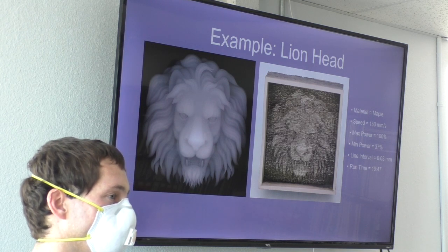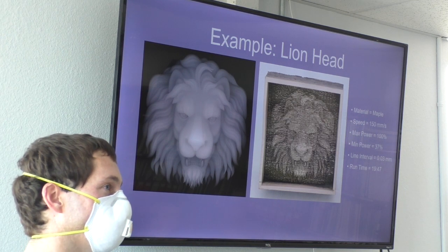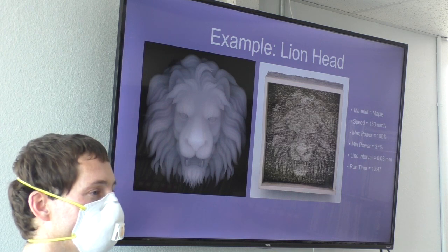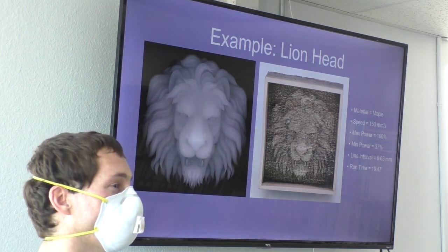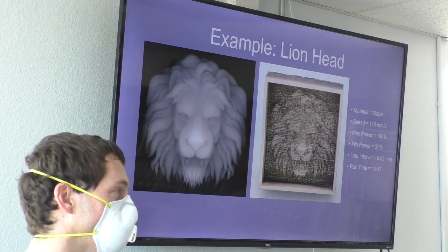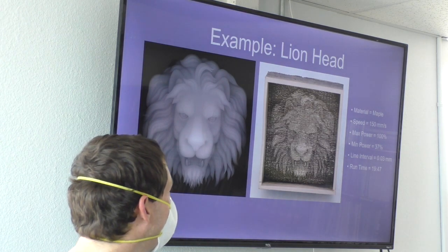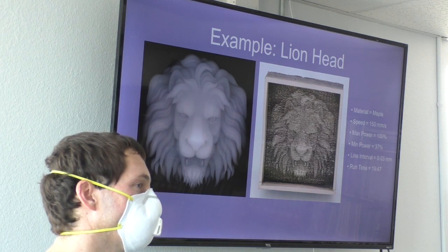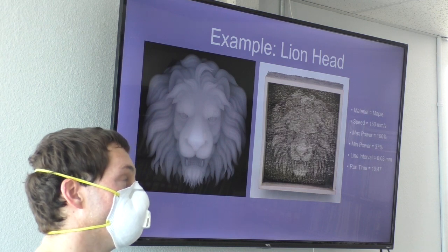So you can't tell it to do the Z axis deeper? No, because the Z depth is totally a result of the power you're using, the speed, and the material. So that's the one parameter that you can't set. With the CNC, you can set the Z because it's physically lowering the head down. But with laser, you're stuck with physics. So the Z is basically set by the color gradient, correct? Yeah. So black, I'm assuming, is what you calibrate to be the highest depth. Yeah, black is the deepest.